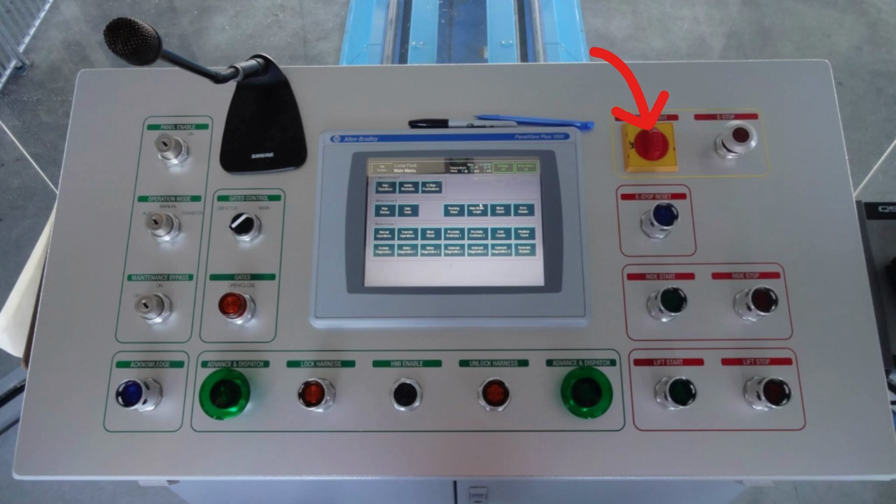This here is the e-stop lockout switch. So in the event a ride operator or a maintenance worker has to go into a danger zone, like say a restricted area or the lift engine, they will turn this switch and put locks on it so that no one can switch it back. And it'll cut off the power to the ride temporarily so that they can do their maintenance and stuff. This here is the e-stop reset button. If an operator or a maintenance crew presses the e-stop button and then they lift it back up, they have to press the e-stop reset button and the acknowledge button, but we'll get to that later, to reset the panel to its normal operating area.